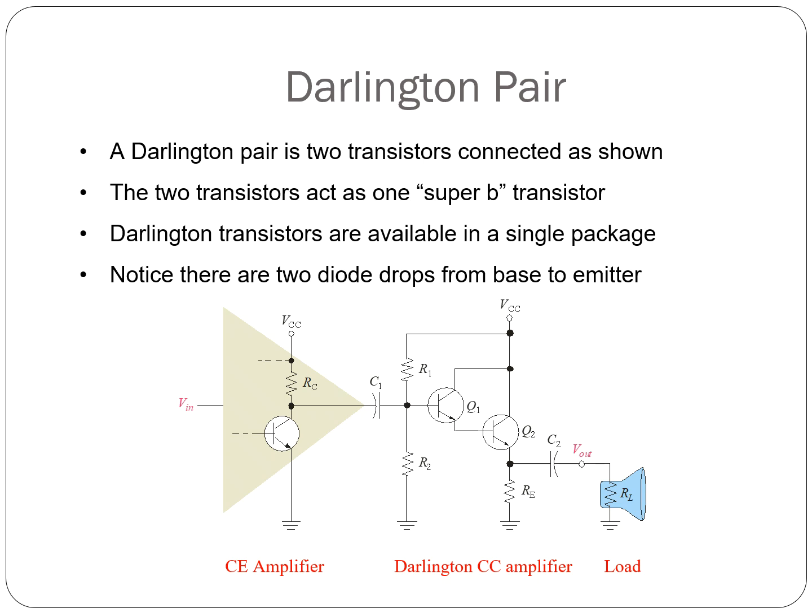So think of the Darlington pair as a relay team. The first transistor starts the amplification, and the second one powers it home. It's perfect for situations where you need high input impedance and high current output with minimal footprint, minimal space required.